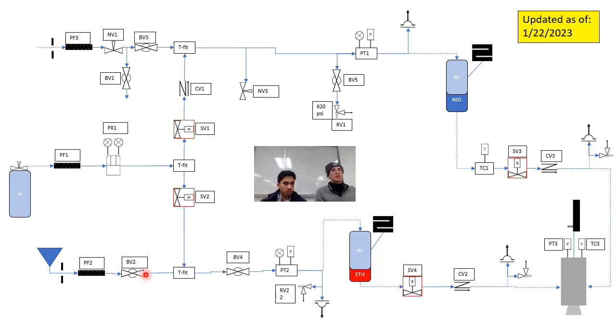The big idea there is, as we're pouring ethanol through this funnel, we want to still keep this system nitrogen clean and free of atmosphere. So we always want some kind of gradient that's pushing atmosphere out, even though ethanol could be flowing in. There might be some way to reduce the risk of bubbles coming in with the ethanol. Not something I've thought about yet, but maybe pouring against the side of the funnel, reducing the risk of bubbles being created and flowing in with it.